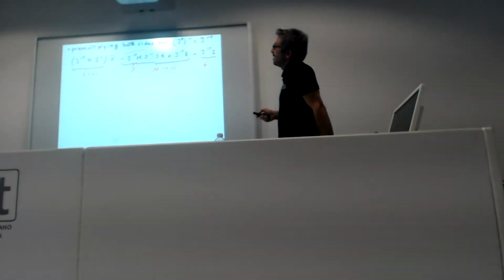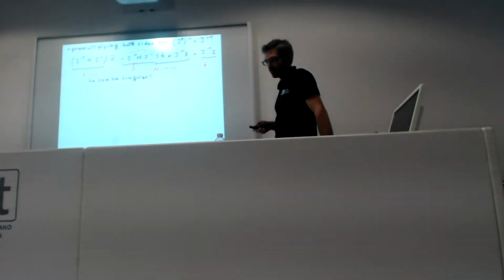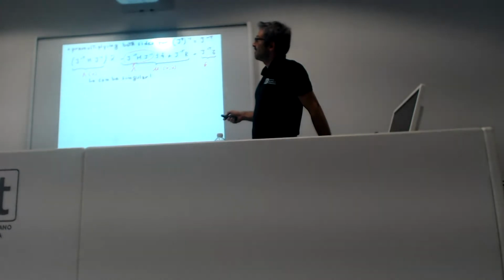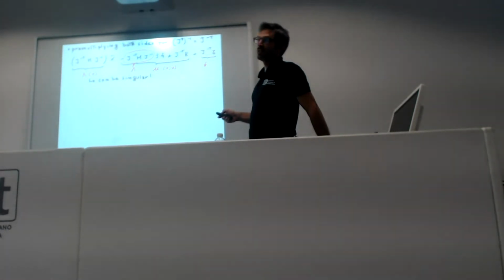And then, multiplying J minus transpose by what was here, you get a term that is called the operational space inertia. That, differently from the joint space inertia M, can be singular.